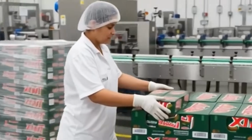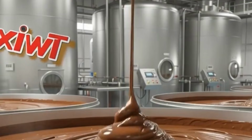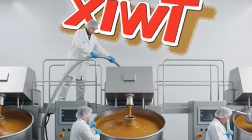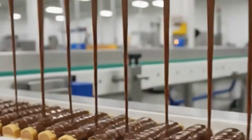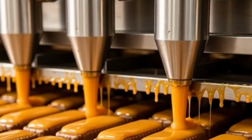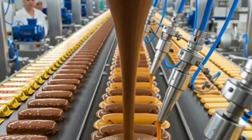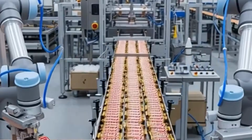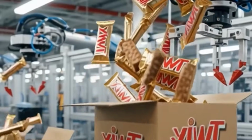The formed biscuit bases enter a continuous tunnel oven with multiple heating zones. Each zone uses indirect gas-fired heat or electric radiant panels to maintain a gradient from 180 degrees Celsius at the entrance to 220 degrees Celsius in the final zones. The baking time ranges between 8 to 10 minutes. Infrared sensors monitor surface temperatures, while dew point sensors control internal humidity. The goal is to fully gelatinize the starch, set the structure, and reduce internal moisture content to below 3.5%.